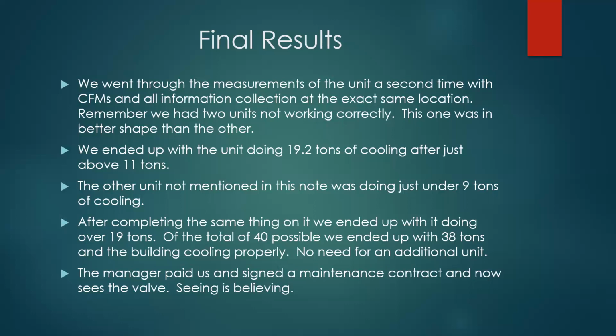The ballroom was comfortable. There was no need for an additional unit. What happened was the manager did pay us. He signed a maintenance contract and now sees the value in maintenance. Seeing is believing. This is something that you as technicians can utilize. You only need something that will measure wet bulb, dry bulb, or what's coming in the airstream, a handheld velometer, or something you can measure your airflow with or calculate it with, and you can move on from there.